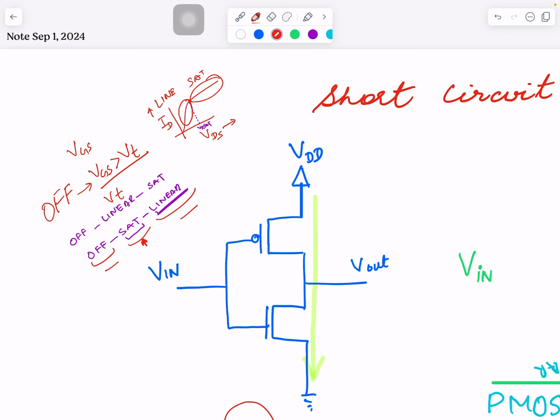This is where things are changing, and the transistor provides a good gain to the input voltage, the input signal, and that's why they are interested in creating that gain, some amplification. So this is the region for analog, and for us digital folks, we're not interested. We don't want the transistor to operate in that. Ideally, if it were up to us, we would skip that.